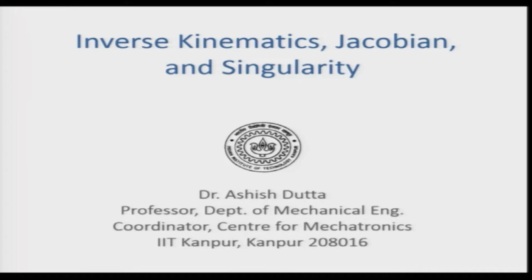Okay, today we will be discussing inverse kinematics, Jacobian and singularity, and very briefly what we had talked about in the last class. We talked about the transformation matrix, how to get the transformation matrix from one frame to another frame, then DH parameters, how to assign axes to a robotic system, and then from the DH parameter table how to use the generalized matrix and get the different transformation matrices.